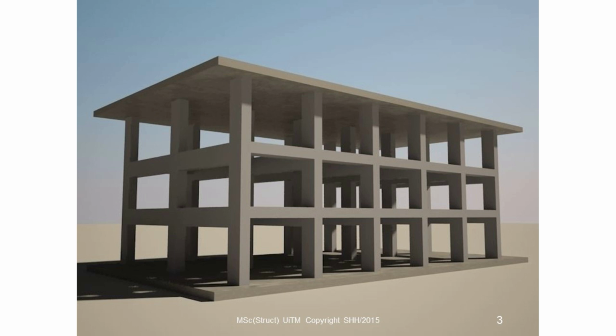This type of structure is economical to about 25 stories only. Above 25 stories, the design will become uneconomical, as it will end up with large member sizes, which are difficult to control drift. Rigid frame is suitable for reinforced concrete due to the rigidity of the reinforced concrete joint connections.